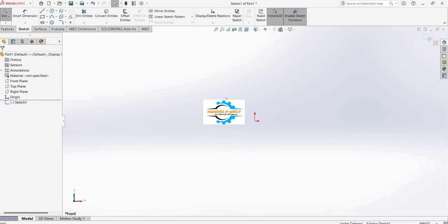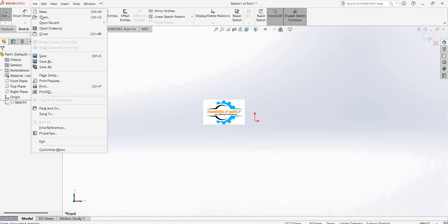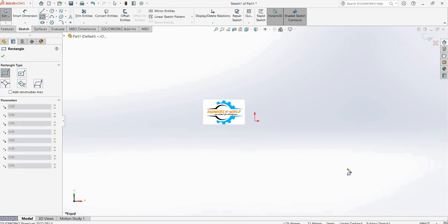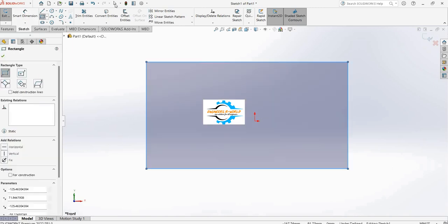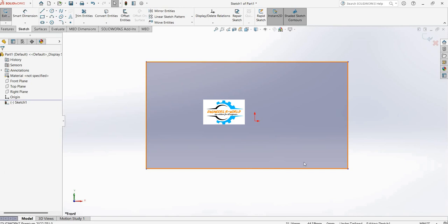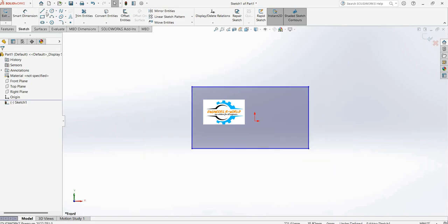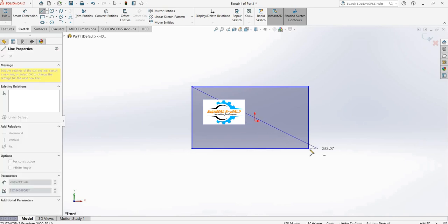Whatever sketch you are creating, it should follow a minimum of three conditions. Those are the three basic conditions. The first condition is that your sketch must be closed. That means whatever sketch you have created, it should be completely closed. Okay, but every sketch is closed. Every closed sketch, or every sketch is closed, the both are not the same.